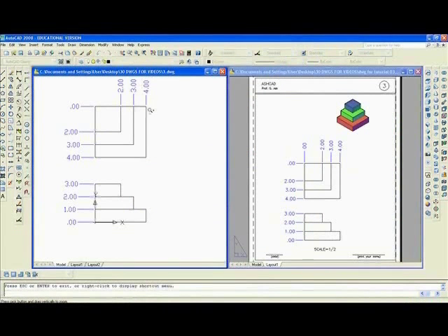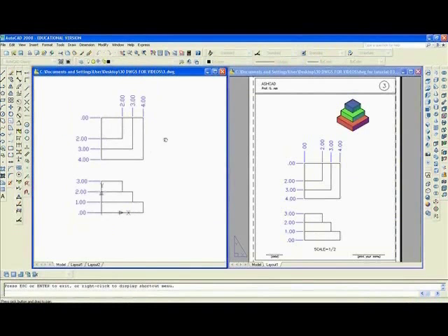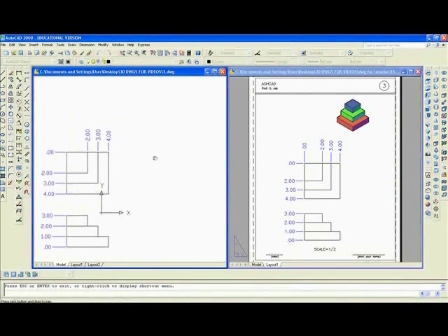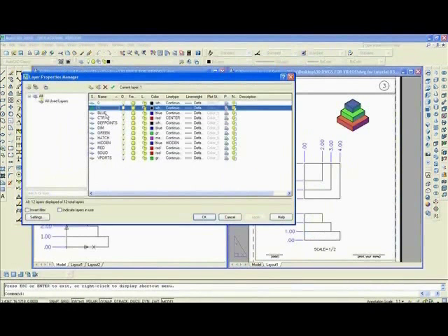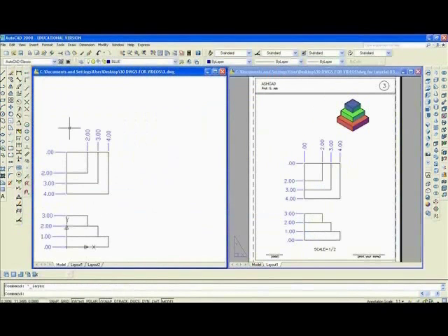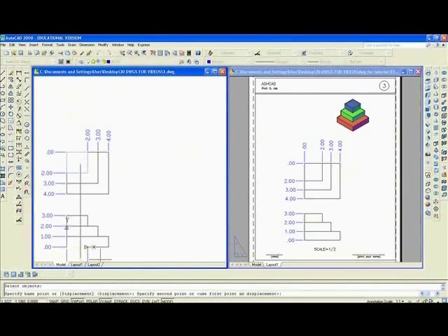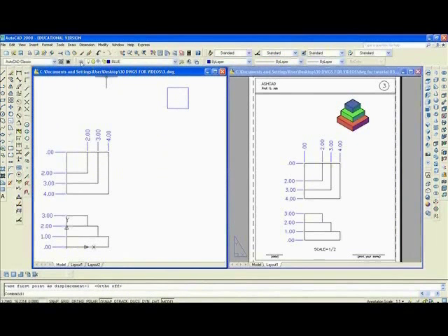Now you might want to zoom real time, then pan to move it out of the way. We have to set blue current, then using the rectangle command pick 2 diagonal points. Here's 1, 2. Now you type M, enter, L, enter. You want to move the last thing you drew. Take off ortho so I can rubber band it there.